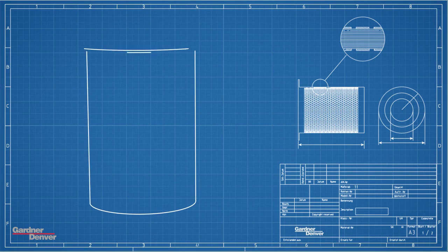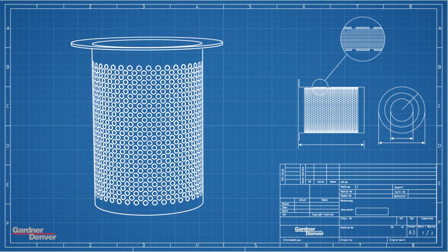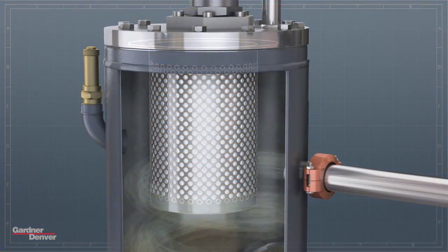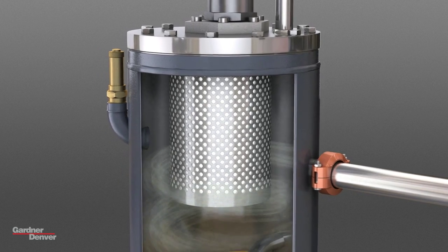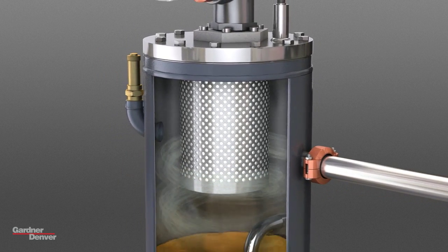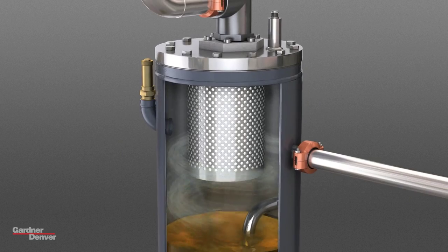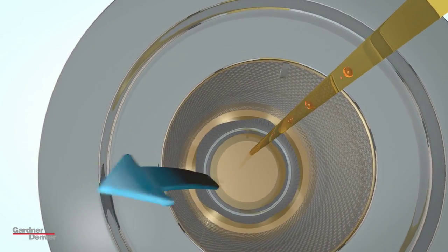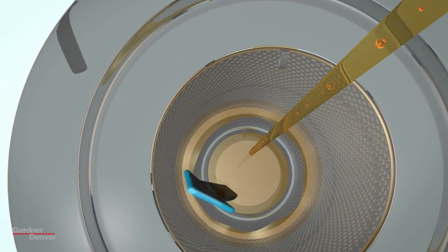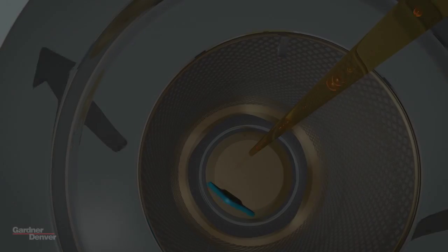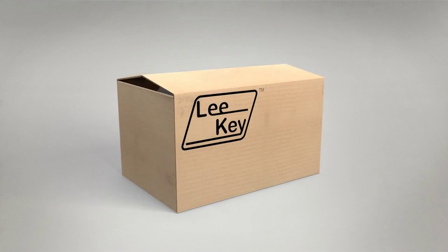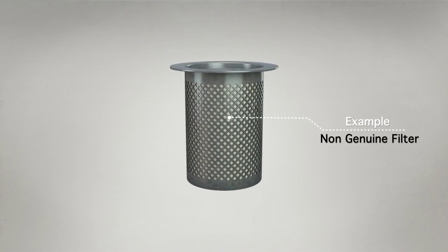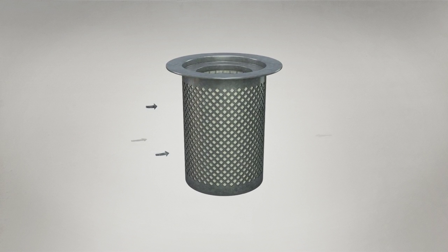In the interest of both cost and safety, it's vital that the air-oil separator in your compressor exactly matches your machine's requirements. Essentially, air-oil separation is the final filtration process within an oil-lubricated compressor. Its function is to extract and liquefy the oil present in the compressed air vapor and return it back to the air end. However, things may not go to plan if this critical component is made from substandard materials or contains unsuitable filtration media.